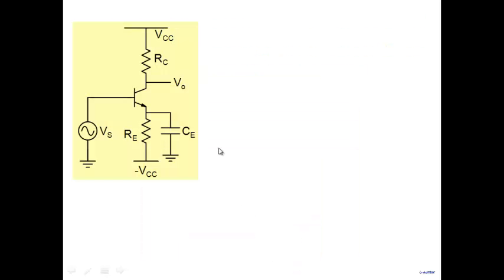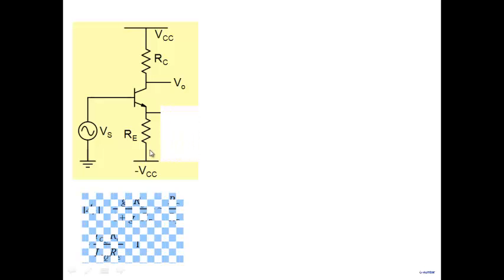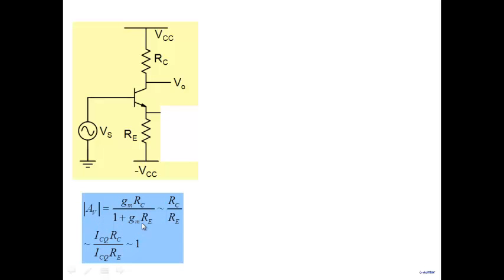But remember, we had a solution where we can take the signal and directly couple it in, and the output also can go directly into the next stage. So the coupling capacitors that you see here, we can eliminate through this configuration. But the bypass we need. If I remove this bypass capacitor here, you know that the gain will become gmRC by 1 plus gmRE.